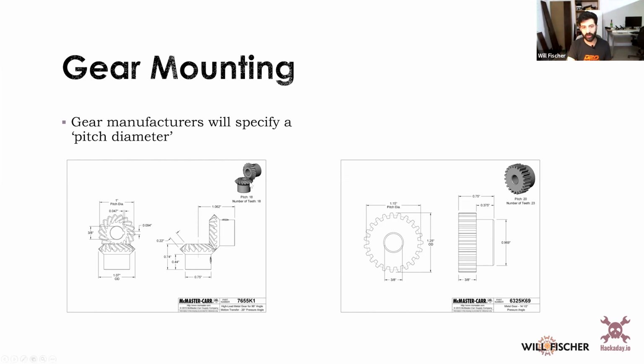Okay, cool. And you notice if I'm looking here, I am showing my tooth pitch here and my number of teeth. Tooth pitch, number of teeth, right? Those are absolutely necessary. And it should show module in there somewhere, but I don't see where it is.